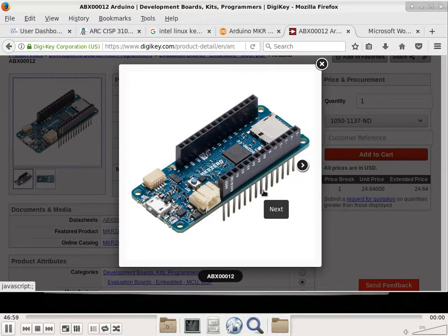But underneath, the chip that is implementing the compass may not give you these things. It may be interrupt driven. In other words, it might take time for that chip to figure out its current heading. So the driver will say, okay, compass chipset, start computing your current heading. But it might take like 50 milliseconds to do that computation. And it's not okay to lock up the processor for 50 milliseconds just to ask, compass, are you done? Compass, are you done? Because within those milliseconds, your processor could have executed millions of instructions. So you wasted a lot of cycles.